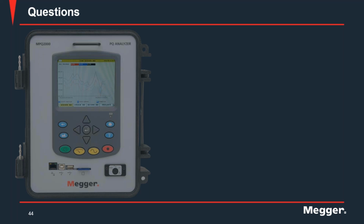But the ideal thing that I would recommend is hooking up an analyzer there and taking a recording of the harmonics. Look at both the input to the rectifier and the output of that rectifier to get an idea of what level those harmonics are at and what frequencies they're at, so we can get the proper filtering on them, because that does seem to be the most likely cause of the problem.